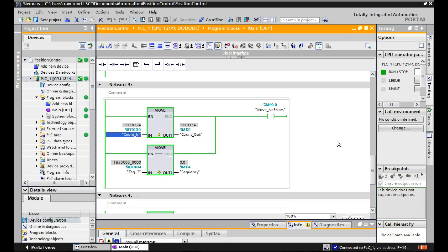So right now we're going in the clockwise direction. Can you see what my counter's doing? Counting up. I'm going to hit switch 4, so switch 4 should clear it out. Can you see what my counter's doing? Counting up. I'm going to swap the directions on my encoder. And what's it doing now? Counting down, because it's a quadrature encoder.